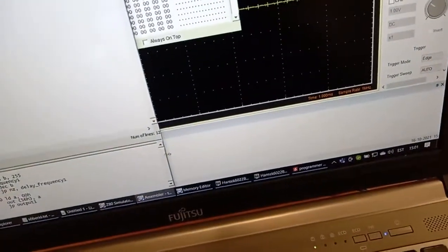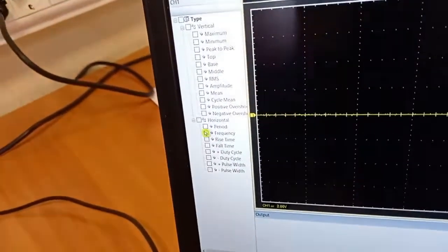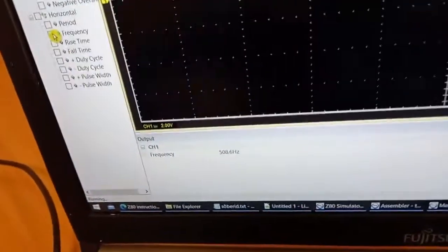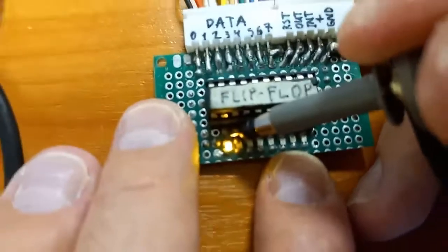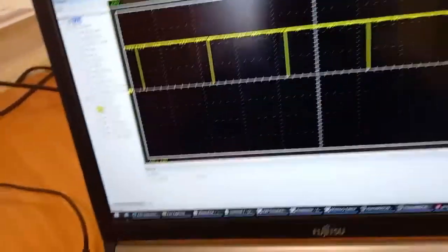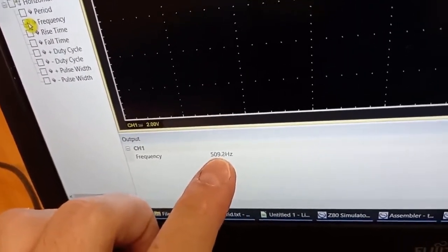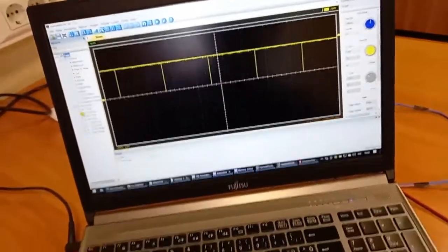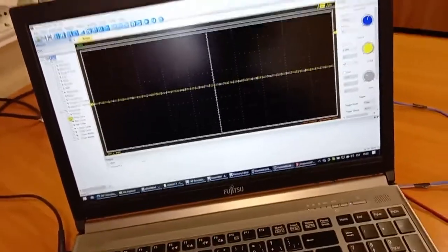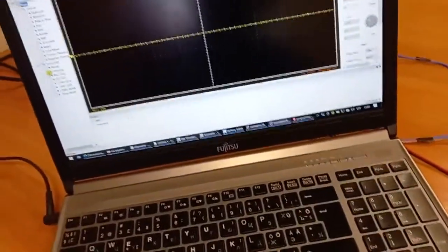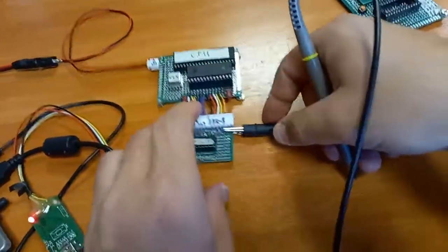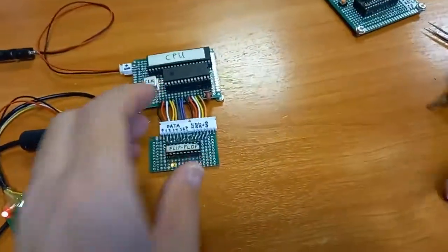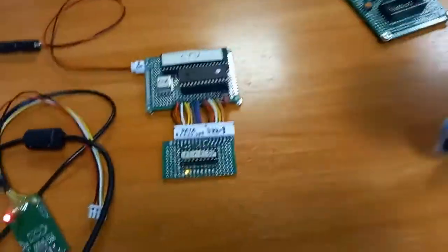And the frequency of these jumps from 0 to 1 must be much lower than 40 kilohertz. The last time we had 40 kilohertz, now we have it connected more reliably. Now we have 500 hertz. Like you see, that's 80 times lower frequency. Thanks to this delay, thanks to this wasting time, we have 80 times lower frequency. And that's 500 hertz is nicely inside this hearable range that we can hear. Now we will hear this 500 hertz.